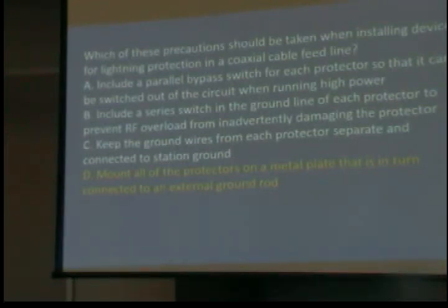One of the neat things that I'll tell you is if you drive the ground stakes close to the house, and the house isn't over 30 years old, that ground is still soft. And by the way, I have a stake driver that will get it down to about this level, and then you'll have to use a hammer.